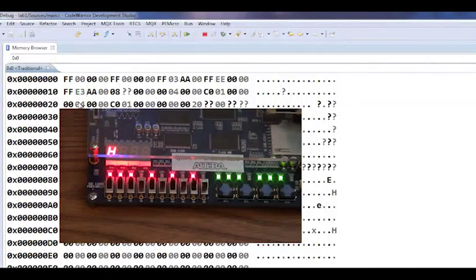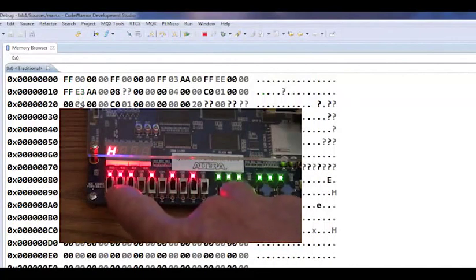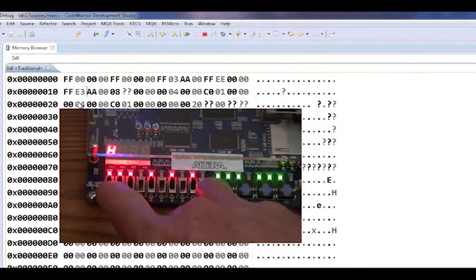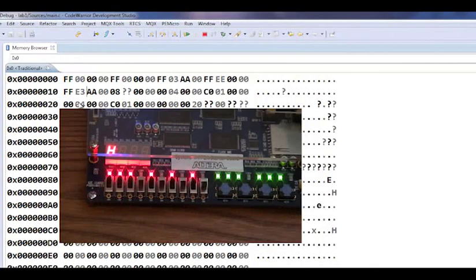And you may be wondering, why are we getting E3? Well, what you're going to find is these 3 push buttons here form the upper 3 bits of this address here, address 11. So right now, if you don't push these push buttons, they're 1, 1, 1, and then there's some no connects, and then these things here. So that's why you're always going to find 1, 1, 1, and then whatever this is the lower 2 bits. And that's basically how our devices work on our microcontroller.